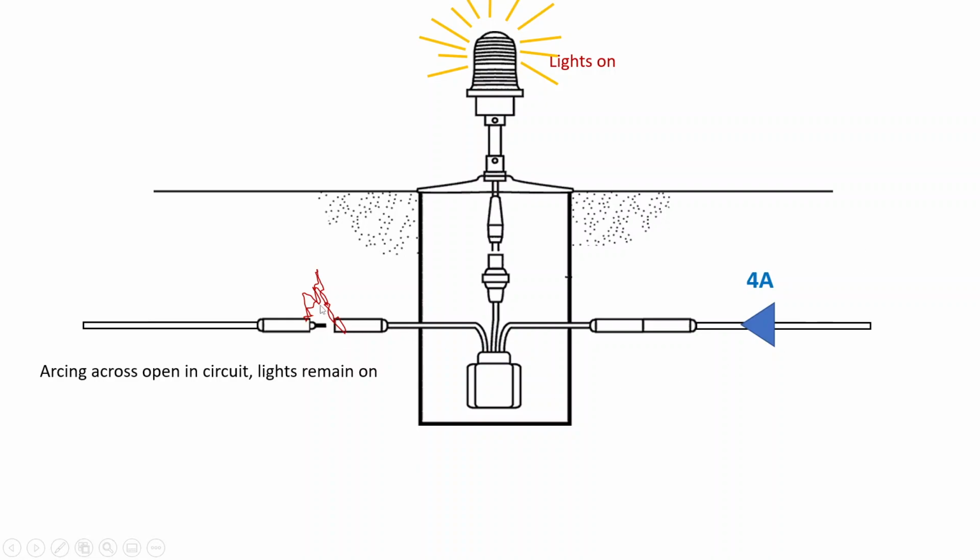So look what's happening now. I've ramped the voltage up so high that it can arc through the soil to the other connector. And why it's permitted is because airfield property is not accessible to the public, and the primary purpose of the system is to land aircraft, not be safe for people on the ground. Now, no overcurrent trips.